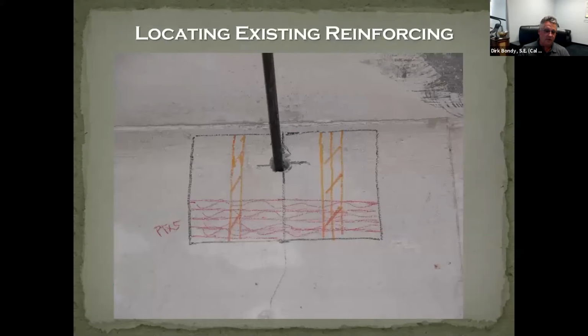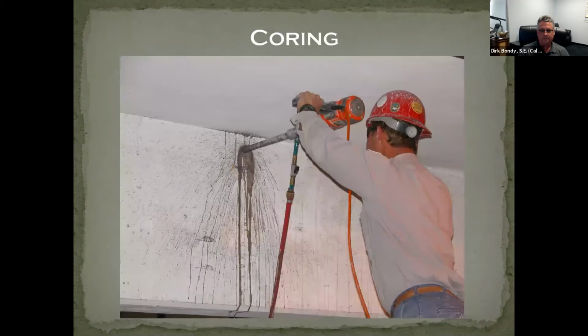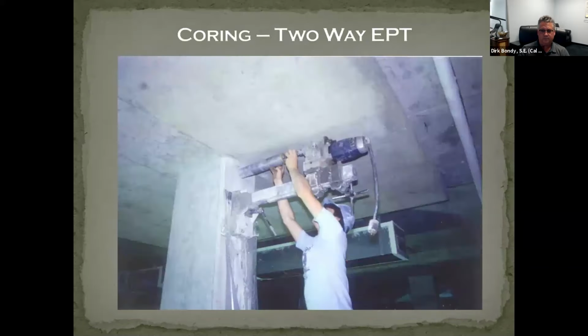It's very delicate because if you're fixing a post-tension building with post-tensioning, you've got to be careful not to make the problem worse. So you need to locate where you have strands and rebar. Get somebody who knows what they're doing to core the system. Sometimes the cores are small, sometimes the cores are large. Now we're always in a catch-22 situation where we're trying not to damage the building too much by repairing it, but locating where the existing rebar is and doing your best to core without losing strength on the element that you're coring is important.